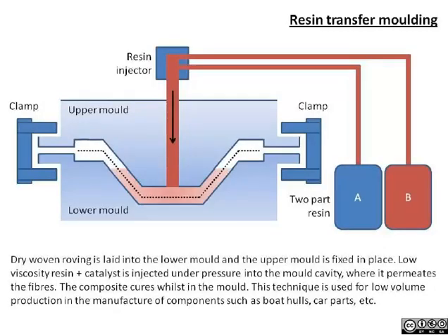If we have a particulate composite, we have the option of, depending on how viscous it makes our resin, pumping a thermoset resin, especially a two-part that achieves its ability to cure when the parts are mixed together, of doing an injection mold. So we'll have a base resin and a curative with whatever kind of pumpable particulate reinforcer in two tanks.